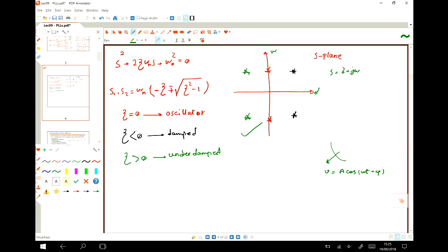This is the LO of our transmitter in the satellite. The baseband data is multiplied by this LO and received in our receiver. So now what should I do? To recover the baseband signal, I need to multiply this signal again by exactly the same LO. True?